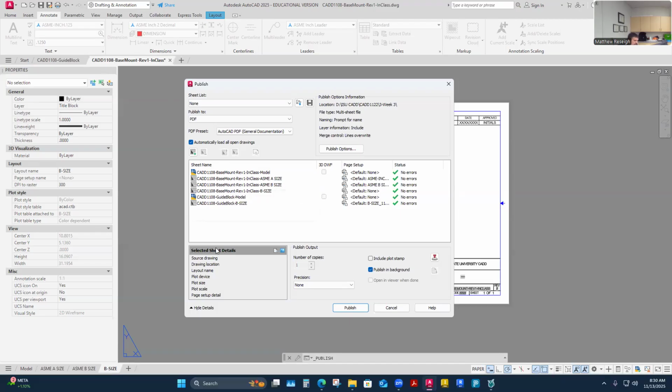And any of them can be turned into drawings, right? There are a lot of people that when they first learn CAD, they just print drawings or make stuff from model space. And we never have, because we're drafters, we do it right. So we're always doing drawings and layouts, and our model space is for the model. But when you go into a batch plot, it will pull in those model spaces as a potential drawing it can make, or part of your PDF package. So what I do first, I get rid of those.